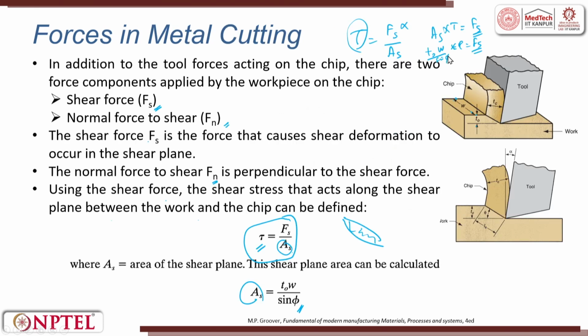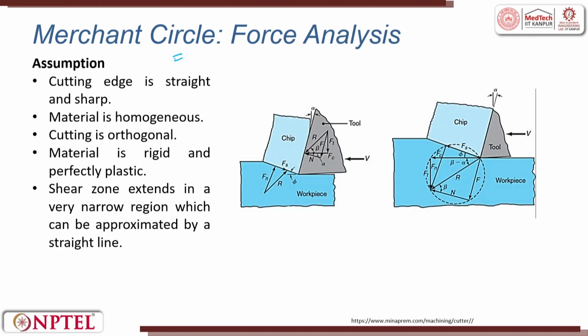The entire thing is derived into a simple form which is called the Merchant circle. Merchant circle force analysis is a very simplistic version through which you can figure out all the forces involved in orthogonal cutting. Before we get into the Merchant circle, there are assumptions which are made, because it is too difficult to do a realistic model prediction. So, we use first principles.